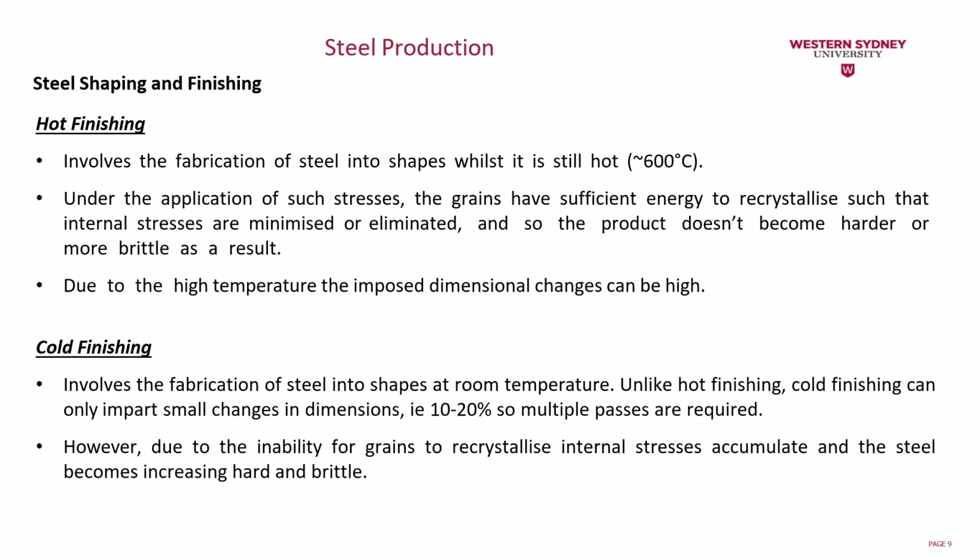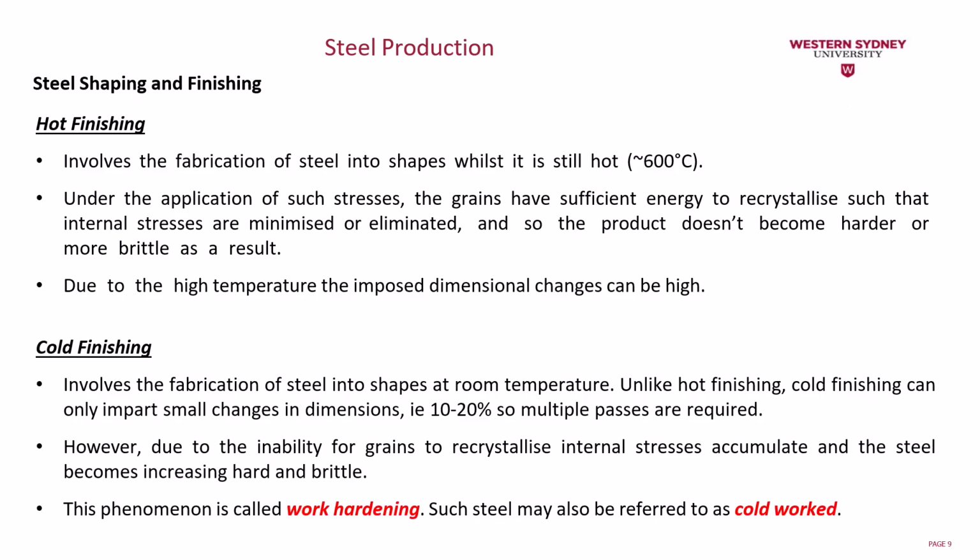However, due to the inability of the grains to recrystallize, internal stresses accumulate and the steel becomes increasingly hard and brittle at the same time. So cold finishing sometimes requires a heat treatment. This phenomenon is called work hardening. Such steel may be referred to as cold worked.